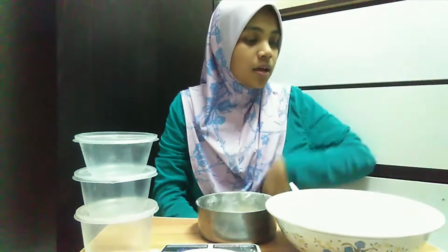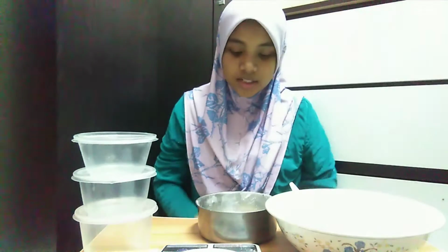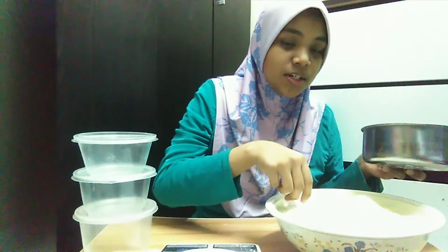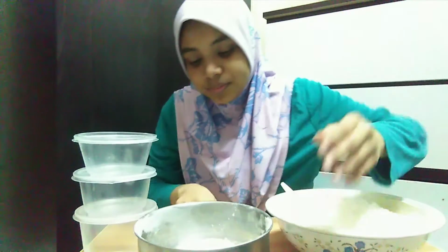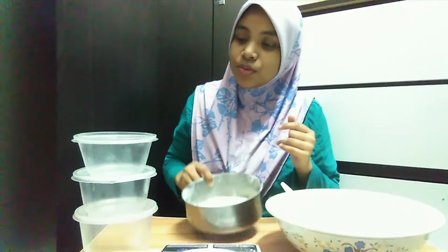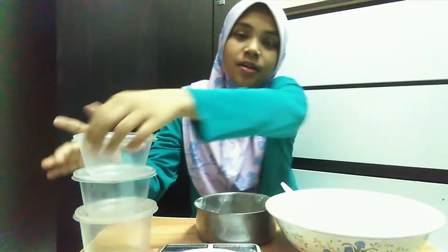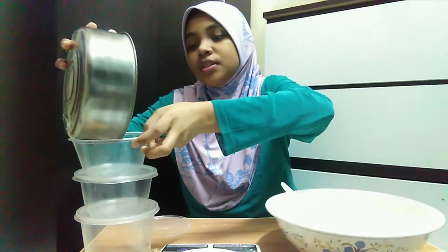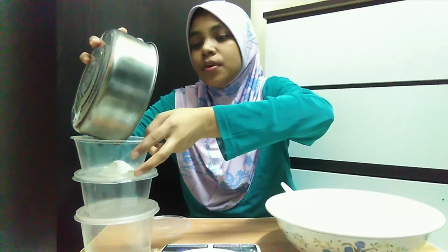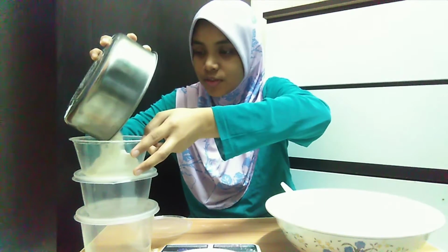For the soil classification test, we use sieve analysis that needs dry soil sample, sieves, and balance. Firstly, we use around 1 to 2 kg of dry soil sample and we take the mass of it. We also need to clean and take the mass of each of the sieves. Next, we pour the soil sample into the sieves that have been arranged according to the size of the sieve opening, the largest one on top of the smallest one.